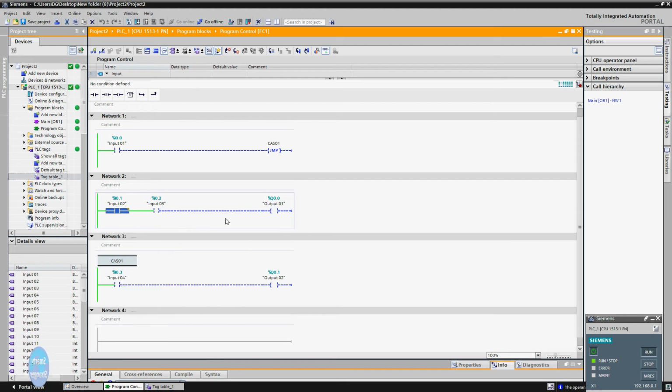Again, check when we energize input 01 in network 01. Network 02 is disabled, and the program cannot be executed in this network. When we energized the inputs in network 02, nothing happened, but the input commands are saved in memory. When we de-energized input 01, network 02 is enabled and the saved input commands are activated.